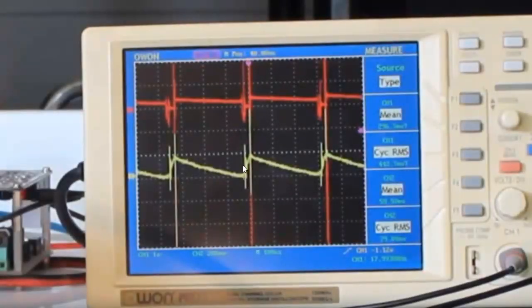Okay, so again, we've seen this before. This is the 10% on time with a 90% off time. From this spike here to this spike over here is off time, but you'll see that's the graticule line, the 0 graticule line for this trace, that this current comes out all the way down to the next switch on. So the frequency would be measured from here to here. That would be 1 cycle, and that 1 cycle consists of an on time, which is the 10% here, and then an off time.